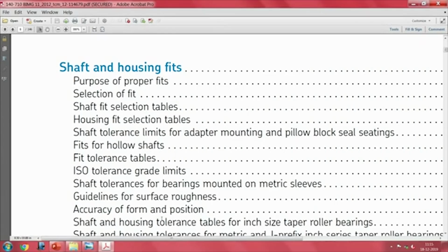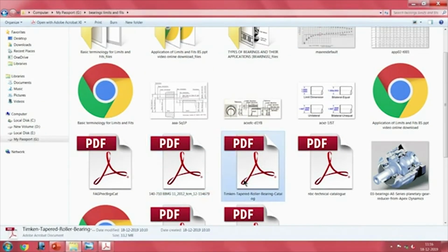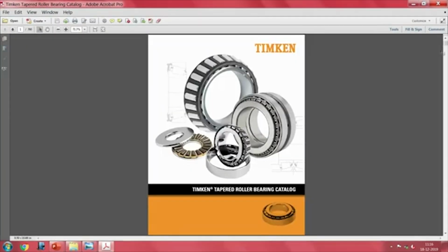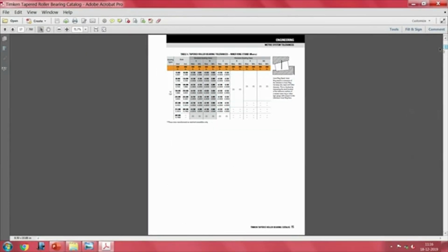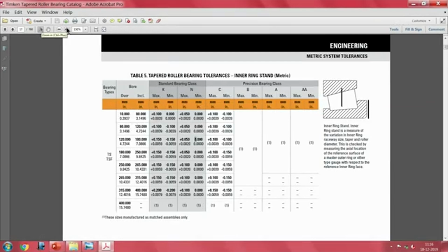Why I am mentioning it is, you can just look around and see how closely the manufacturing follows certain standards. And let us say you do not get any one of the original bearings, or you have opened an old housing, or you want to make alternate sources, each of these manufacturers also give you this. You have seen this, the best 4 of them which I have managed to get. There are standards meant for even roller bearings. Now, understanding and going through these engineering manuals, it is easy for you to carry out your design.